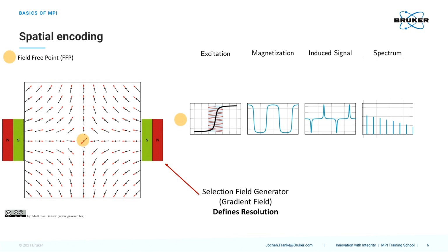As we are talking about magnetic particle imaging, we need a kind of spatial encoding, right? So we don't want to characterize the particles only. We want to measure the distribution over space. So what we can do, we can take two magnets facing with the same polarity to each other, forming this magnetic gradient field. And I have brought kind of a similar representation here in hardware. And what you can see is that these fields cancel each other at the very center. And this is called the field-free point, or generally the field-free region.